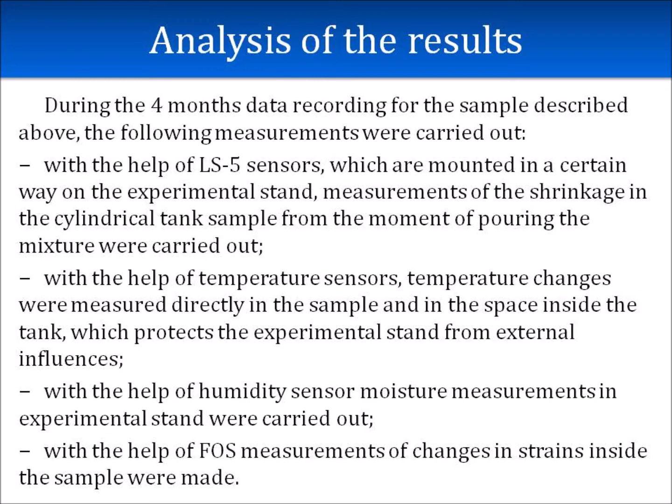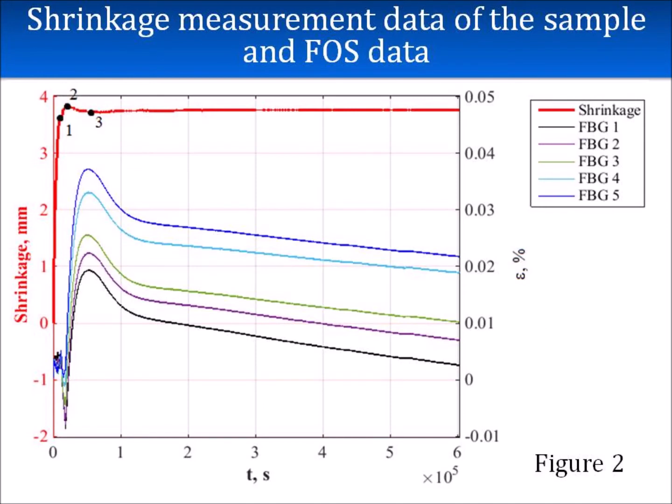Analysis of the results showed the following. Plastic or capillary shrinkage of the sample was realized in the first 3 hours of the experiment and was about 3.6 mm. The shrinkage graph at this stage can be seen in Figure 2. Its end corresponds to point 1 in Figure 2.